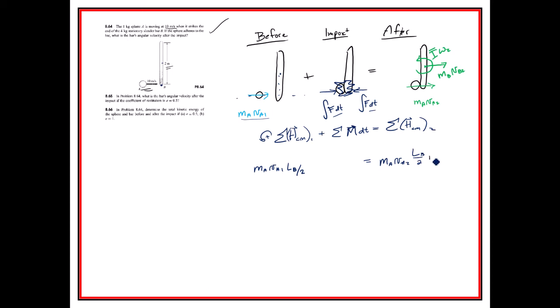But then we're also going to have the mass moment of inertia right there. We could find that mass moment of inertia over on the side, 1/12 m LB squared. The mass, I said, was 4, and the bar was 2 squared.